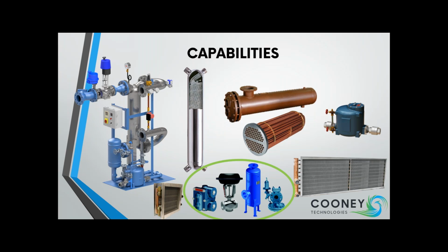The next we're going to look at, upper right side, is a motive steam condensate pump. In the old days, you only had the mechanical electrical pumps that would have a float inside. Condensate level rises. If you have a duplex pump, you would have a lead lag controller inside. The float would kick on. If it can't keep up, the second pump would kick on.